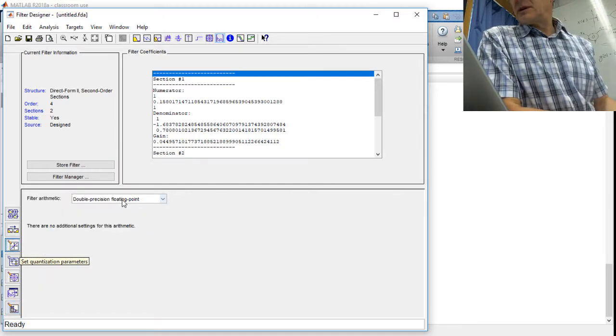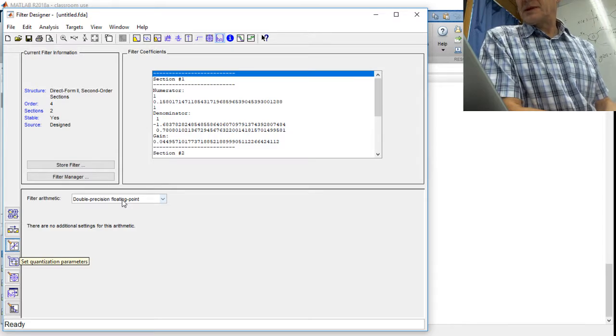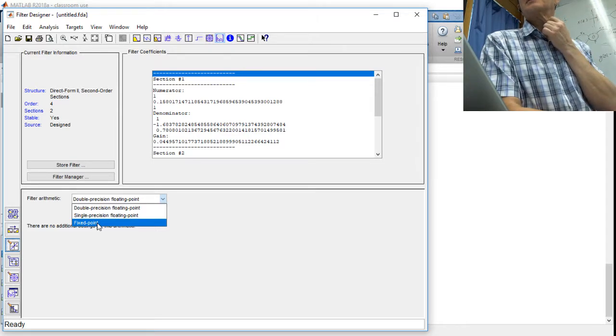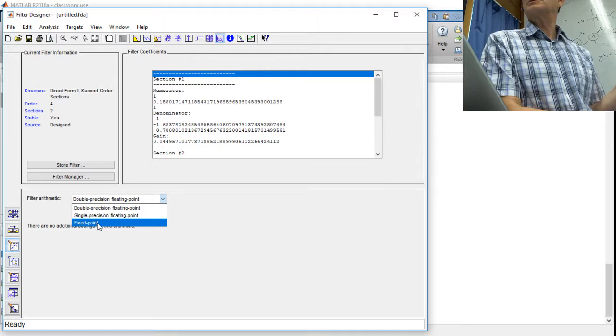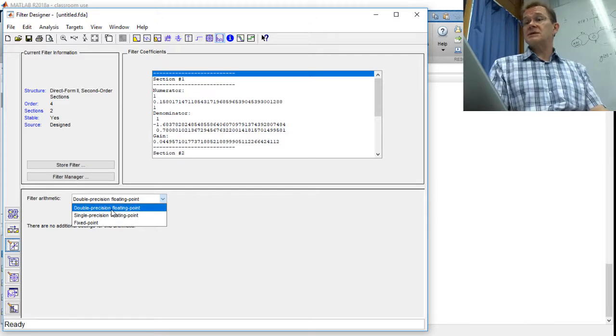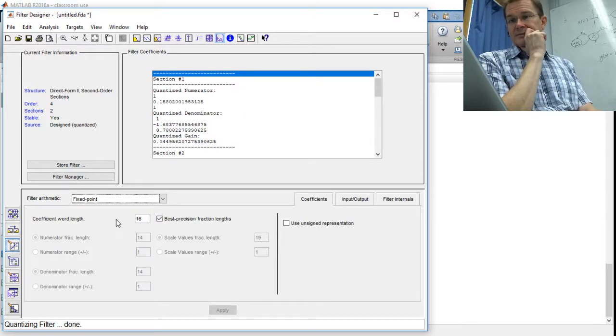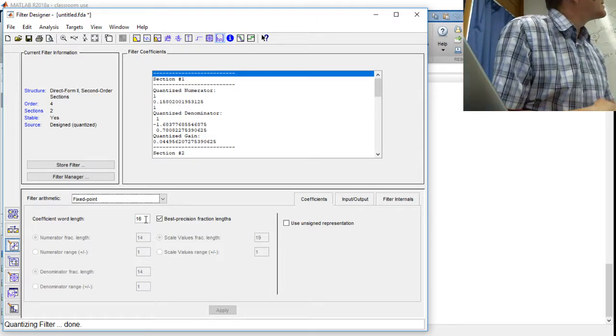Now everything is done with double precision floating point numbers. But you can also see what if we go into fixed point presentation, meaning signed integer calculations. In small microcontrollers without a floating point unit, that would be the only way to go, since software floating point calculations would take way too much time. So fixed point arithmetic, and we have 12-bit data, so 16 bits should be enough.